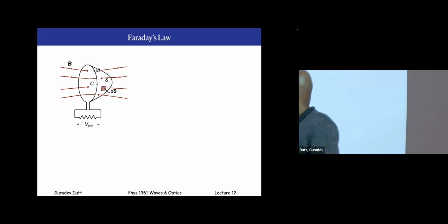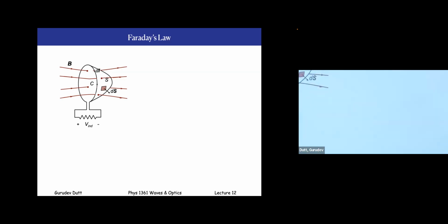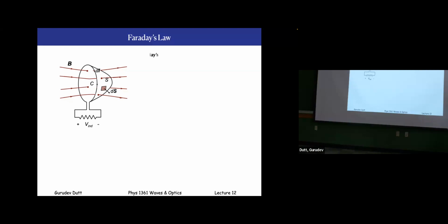You can do lots of different things, but the point is, as soon as you move a magnetic field or change the magnetic flux through that loop of wire, you get an electric field, or essentially an induced voltage across that wire, which usually causes current to flow. When you write that down, the induced voltage is negative because it always opposes the change in this flux. The changing flux gives rise to an induced voltage across the terminals of this loop, this contour or circuit C. And psi, as I said, is the magnetic flux that goes through, or links, that closed loop C.